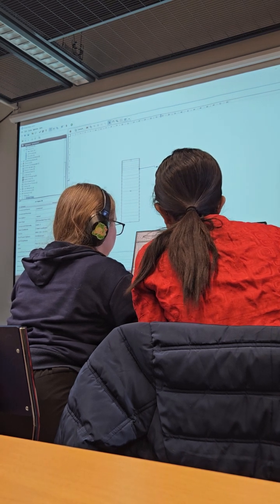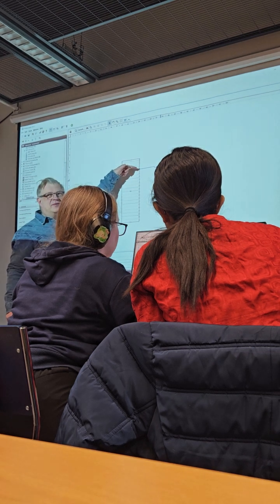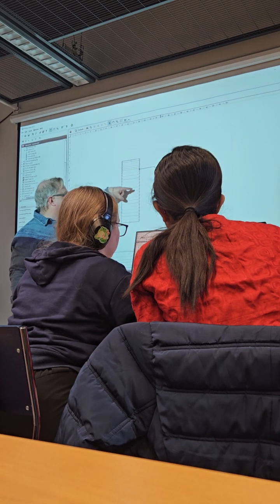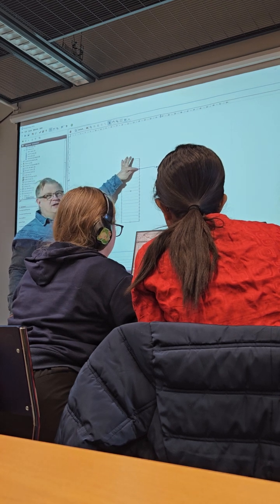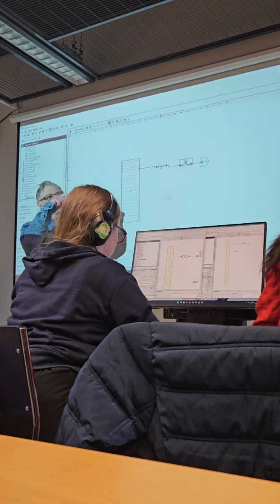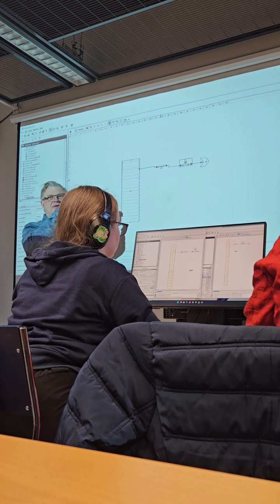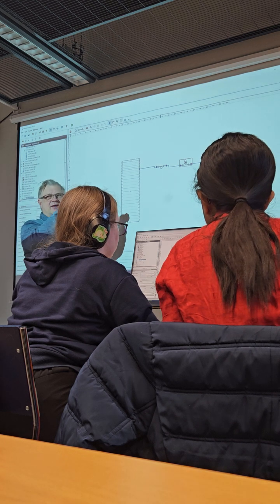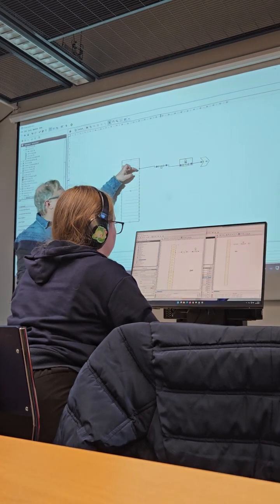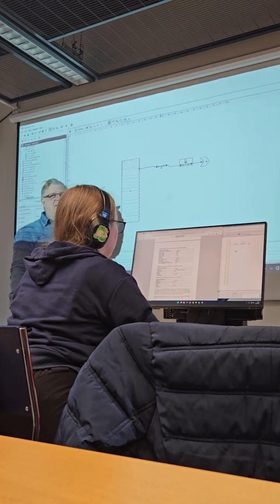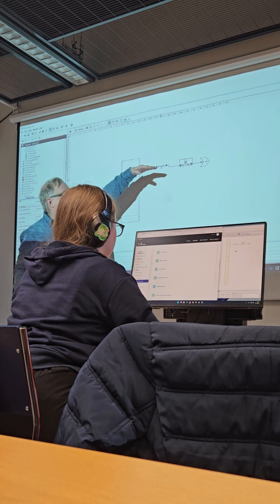Where this actual line is connected, then it should be at 10 meters. Okay, exactly. So you have to calculate how long each node is, and because it's in a half, in the middle point of the node, that's also 1/2 of this node length. So the middle node should be 10. Yeah, so you need to make these nodalization changes, you need to adjust that it's in the correct position.